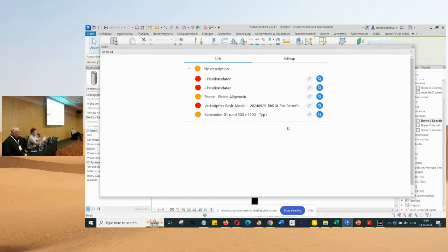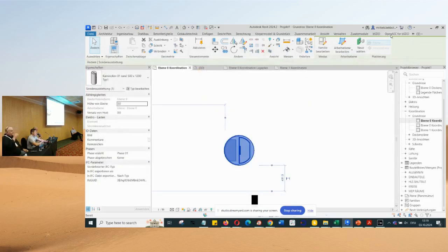If you use, let's say, aerated concrete walls, you definitely need to add their specs, the lambda values, and so on. In that case you can make a simulation. But if you do a simulation, for example in a system build, you're going to find out it's really hard to define what kind of airtightness the existing building has, or you have to do a blower door test, and then you're adding a lot of cost to that project.